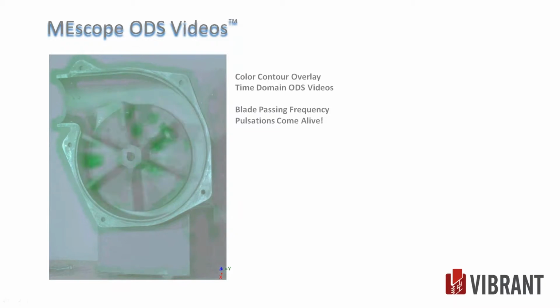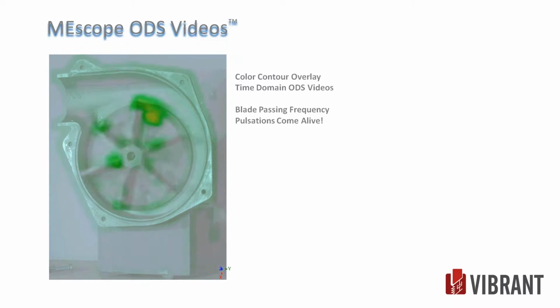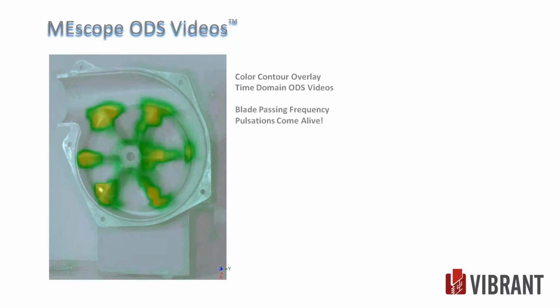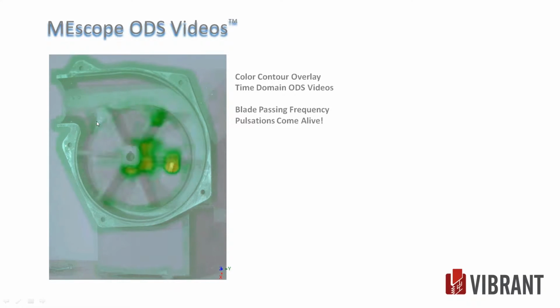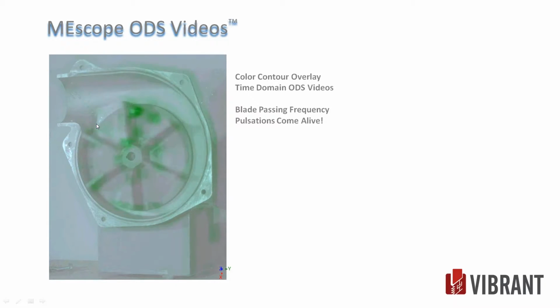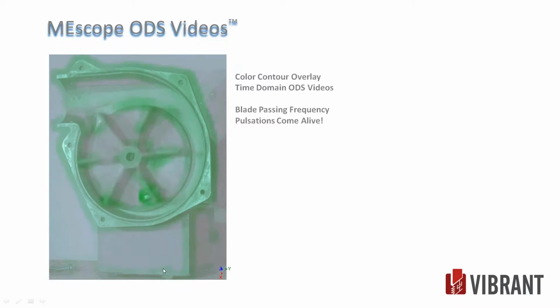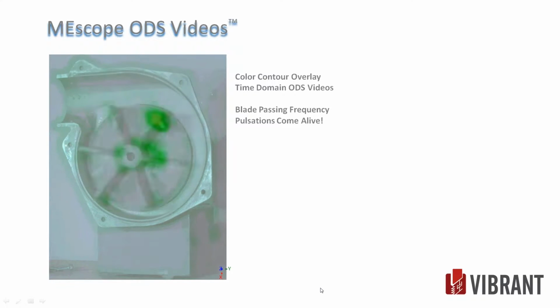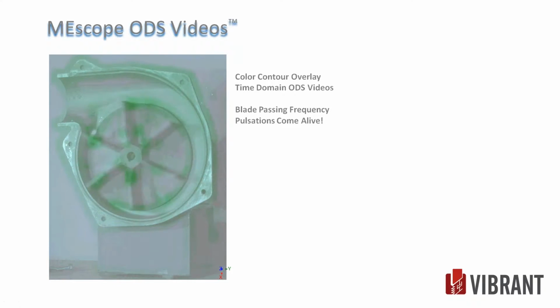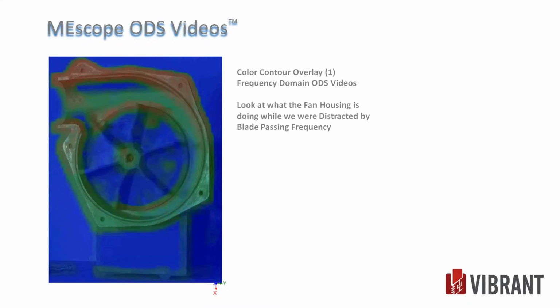My thought is it's probably the natural frequency of the paddle, and it rings it like a bell when that little blade pass frequency pulsation hits. And it's highly damped, so it recovers quickly, but just an interesting animation. I've never seen anything like that before until the next one I'll show you.